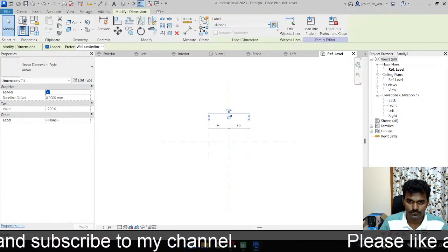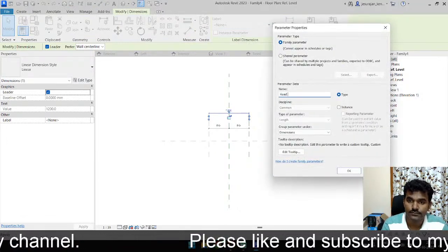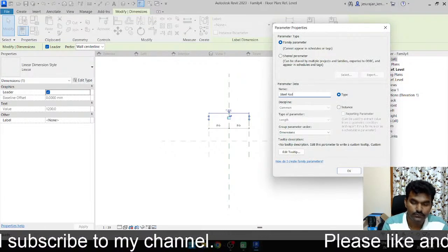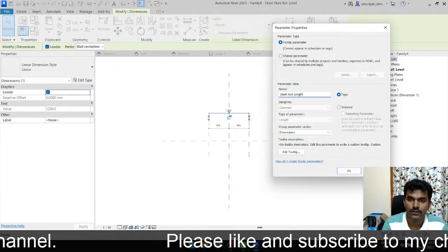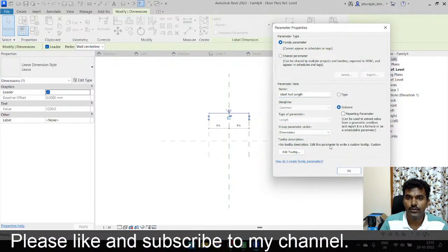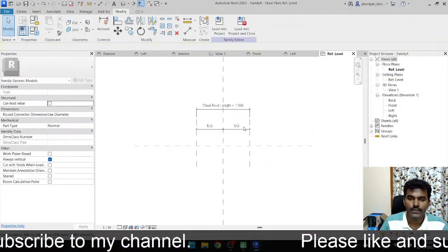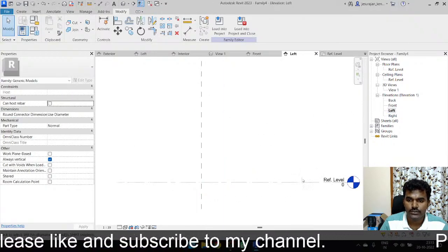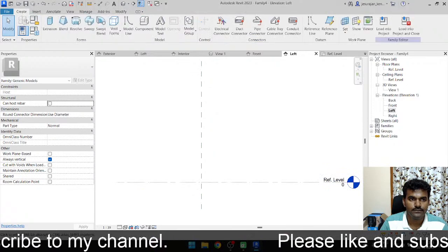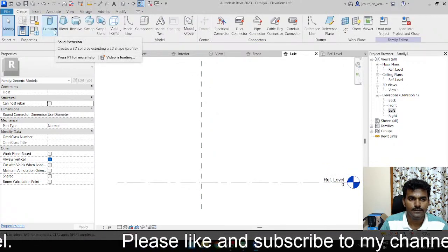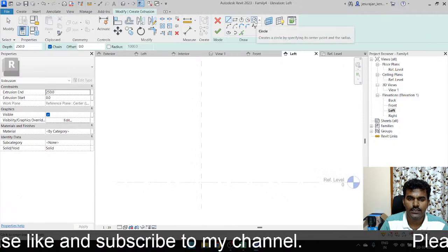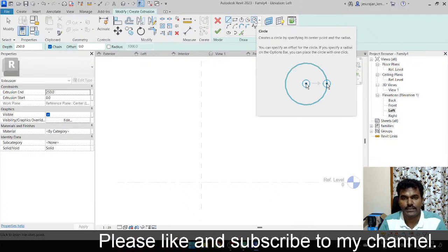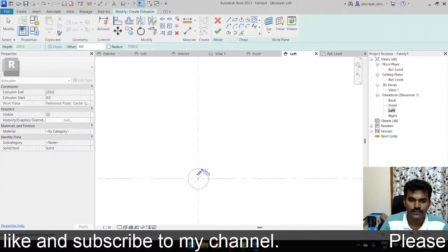Create a parameter, steel rod length. Okay, so length is done. Then just go to left. Let's just draw it in the reference level itself. Go to create, extrusion. Should we draw it with extrusion or with the sweep? What do you think? I think the extrusion will work fine.